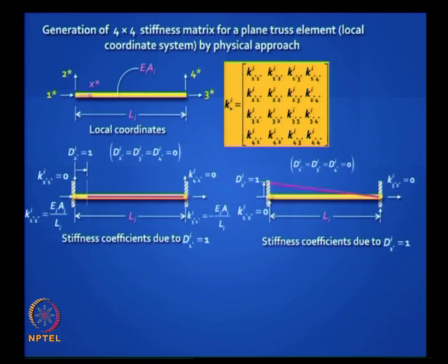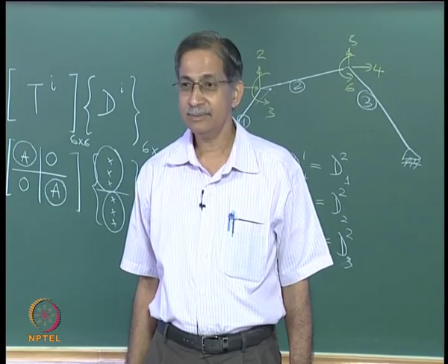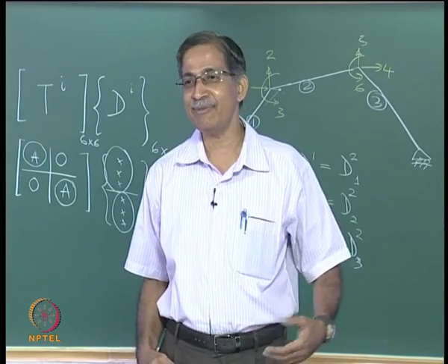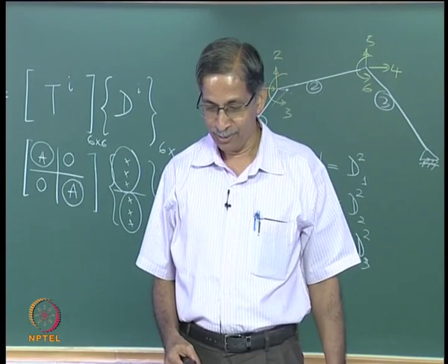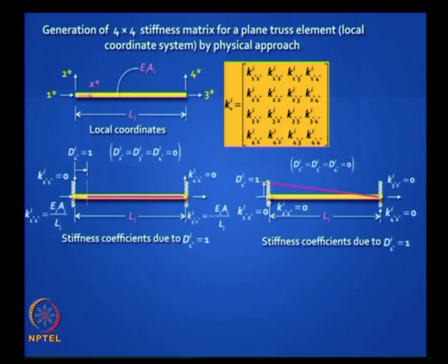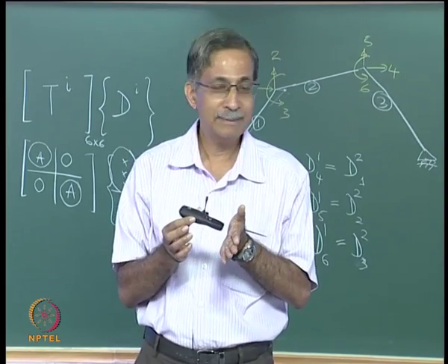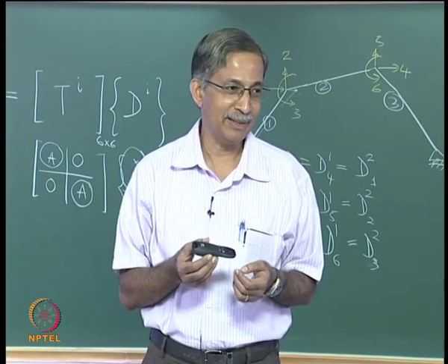You see, all you have to do is to lift it up. Yes sir, like a rigid body. Then what? But why not displace it? That member has stiffness only along its own axis. So he gave the correct answer. All you do is to lift it up. It will move like a rigid body because you are allowing that movement, and it's pin jointed. See, the first thing you learnt was in a truss member you will have a force only in that member. There is no shear force. There is no shear force in a truss member. So how can you have a non-zero there?